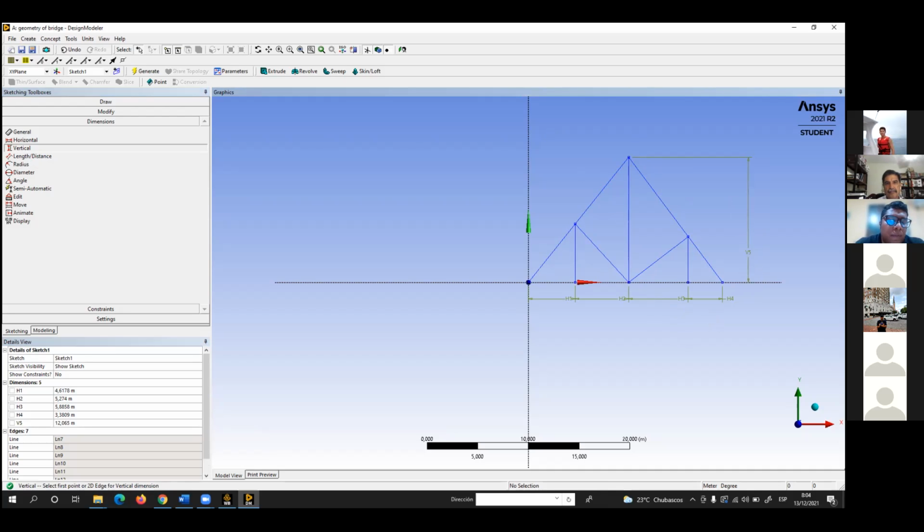In this form. Next, you have to input the value. Remember the value of the horizontal dimensions. Every horizontal dimension is 2.5. In ANSYS, the decimal uses a comma, not a point. So remember that the decimal uses a comma, not a point or a dot.